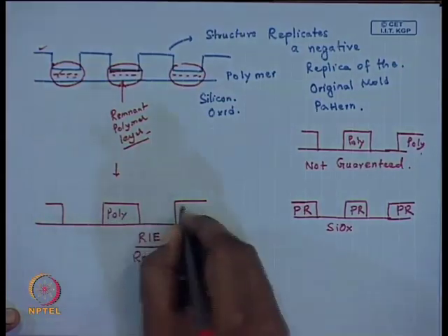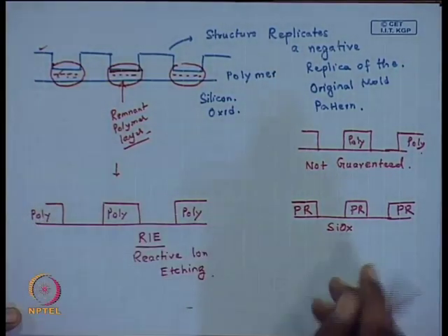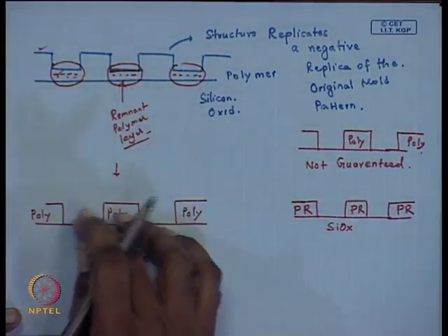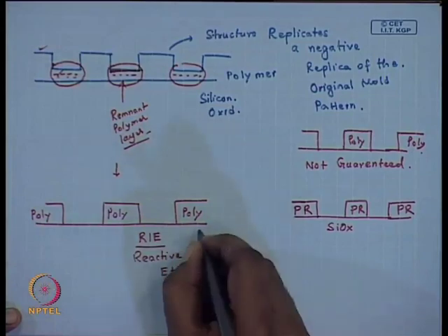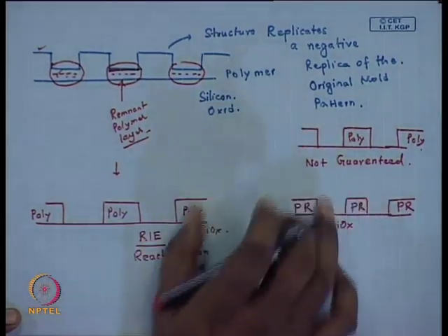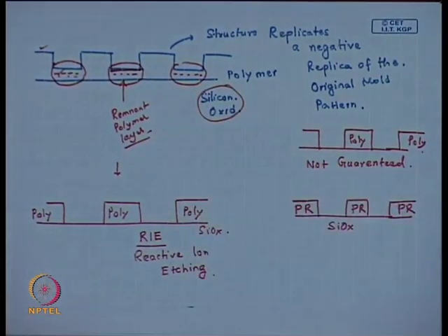If you compare with photolithography, in conjugation with nano imprint lithography and reactive ion etching, you can go to the same stage, and subsequently what follows is etching. If you have the oxide layer, you can do the etching and have direct access to the silicon surface and follow it up. Then it becomes very similar to the later processing stages of photolithography itself.